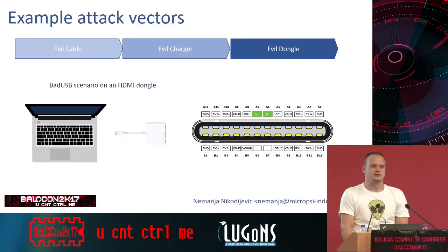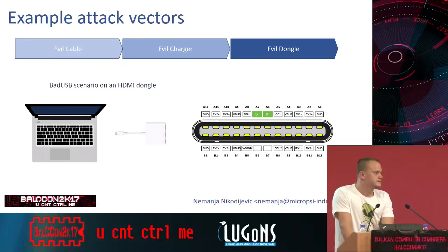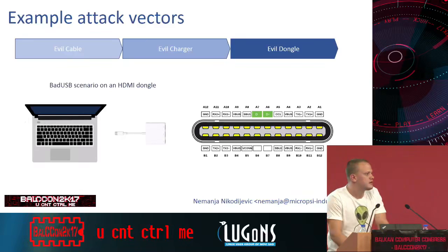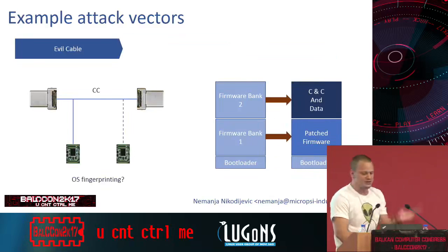Okay. Any other questions? Yeah. When you change the ID of the device, is there a possibility to roll it back? Yeah, of course. You flash it. Is it saved somewhere on some ROM or other? Well, of course, there is this dual banking, so I change it only in one firmware bank, so I can always revert to it. You can roll it back, so I can read the real hardware ID from that chip, from that device. Yeah, of course.